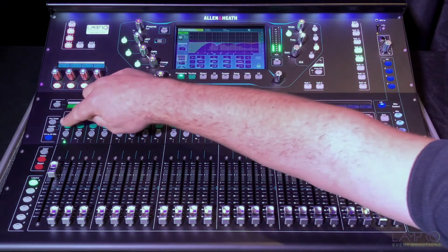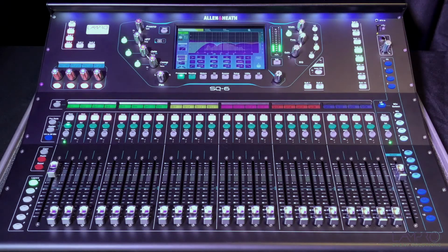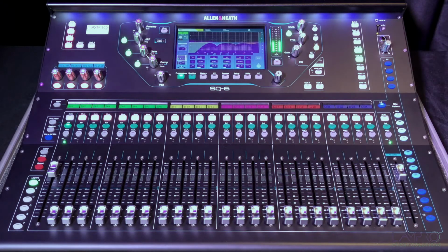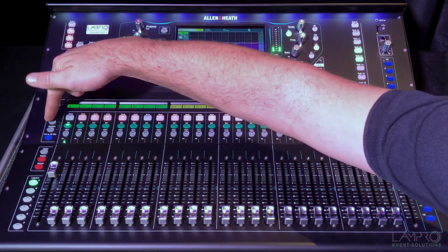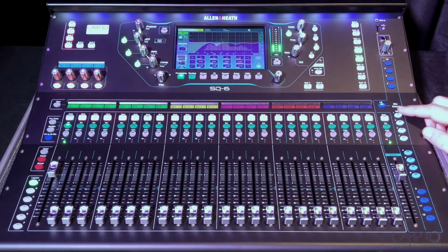The pre-fade button over here is used to show and assign any of the channels to either pre- or post-fade mode. The channels that are in pre-fade mode will have their select buttons here illuminated. Since we're using the main mix in post-fade mode, the select buttons are not illuminated when holding in the pre-fade button. On a pre-fade aux, they will be illuminated and can be changed to post-fade by holding in the pre-fade button and pressing the select switches.